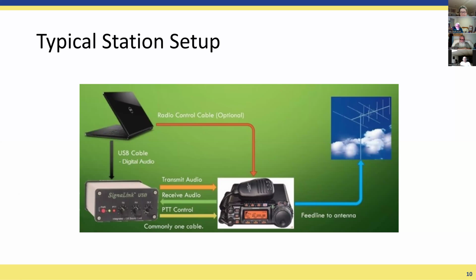Now, the radio I have, whose design is about 5 years old, just has a USB cable that connects right to the back of the radio, because this audio interface is built into the radio. You'll find that sometimes people use the headphone and microphone connectors on their computers directly, but most people use some sort of external sound card or audio interface box. And you can theoretically use just about any radio capable of transmitting single sideband with one of these and work digital modes.